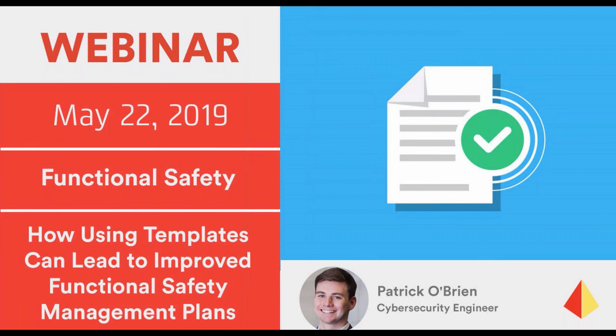This question is, the FSM document does include the SRS, and yes, the safety requirement specification, we have a group procedure for that. So we have the procedure that would be followed to go through and document the safety requirement specification. We've also included a template within that, actually a table format of where all those requirements can be kept. In addition to having that individual procedure, it is required and referenced within that overall functional safety management document. So that is one of the key activities that is called out and looked at.